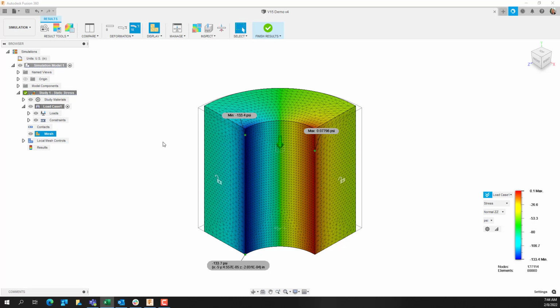So between your first mesh, you get a result, and your second mesh, you get a result, but it changes. And then between your second and your third result, if you are decreasing the mesh each time, hopefully what you are seeing is, it's converging upon a solution. That is, the degree of change within results from mesh to mesh is getting less and less, indicating that you are getting closer to the solution.